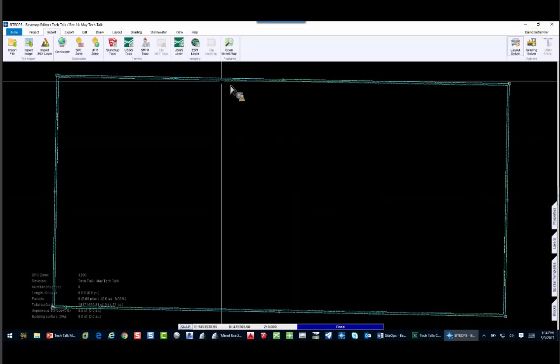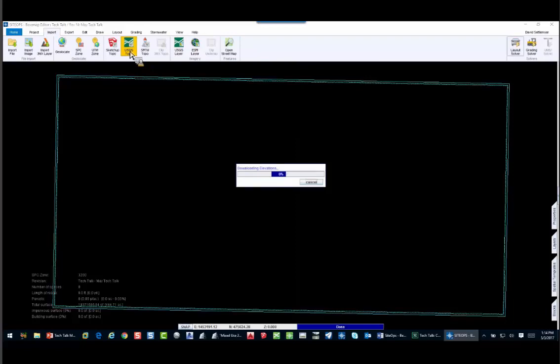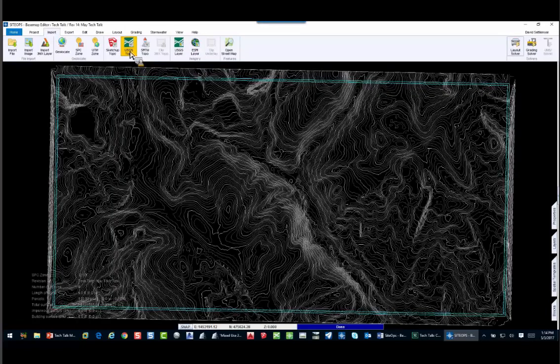Right now, I want to come in and let's get a topo. So I want to go to USGS, click a button. Just a few moments, less than a minute, I've got a surface. Now, I've also seen the contour. So again, everything we do inside of SiteOps today is going to look two-dimensional, but in the long run, we're doing it in a 3D form. We try to make it nice and easy for the users. So again, they more worry about designing, like I said, and less about drafting and less about making a model.